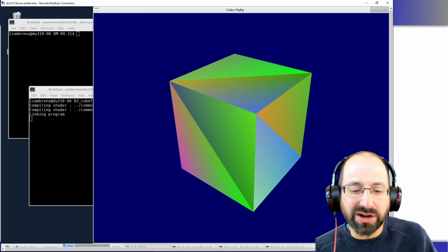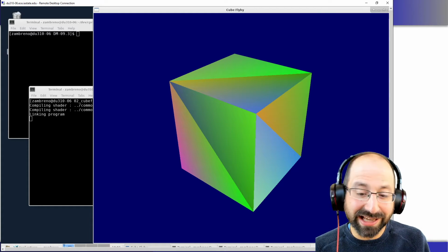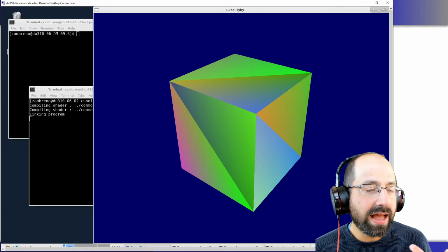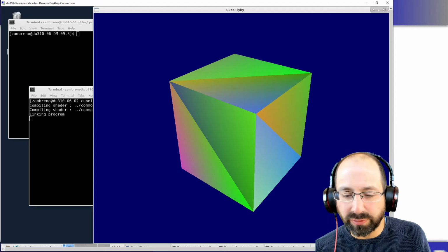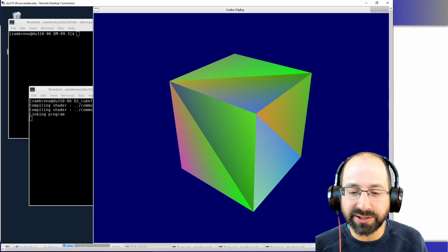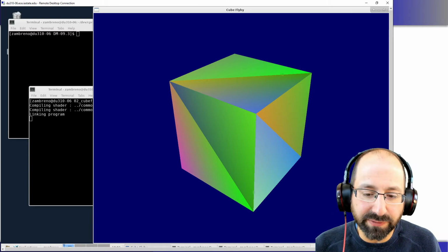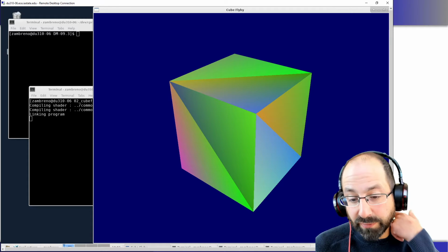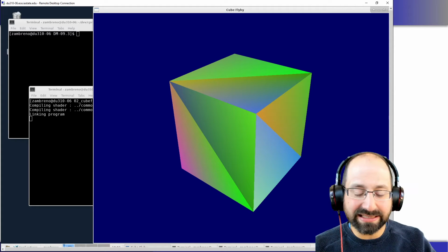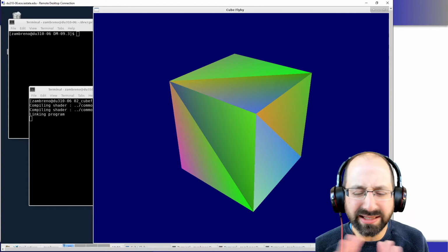It just tends to be a lot easier to talk about things in 2D first, to test things in 2D first. And then as you add that Z dimension and you're actually using that information in MP4, things should just sort of work. You may have to go back and look at, well, when I rasterized, did I just ignore the depth parameter? I don't think most any teams did, but that's a fixable mistake if you did that. But we are doing 3D stuff. It's just when you're testing, and certainly when you're testing with ILA and you're trying to grab and test individual instructions running on your shader, keeping things as simple as possible is still very much the way to go.